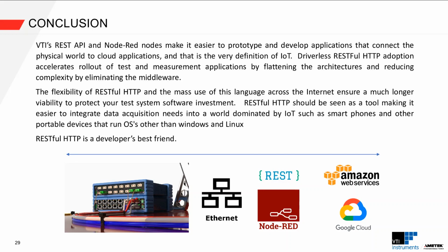Driverless RESTful HTTP certainly helps accelerate the rollout of test and measurement applications, and it does that by flattening the architecture. What you're doing when I say flattening the architecture is you're missing out the middleman of having to use drivers and learning everything that goes with a particular manufacturer's driver. You're going straight to directly controlling the instrument via a globally accepted communications method.